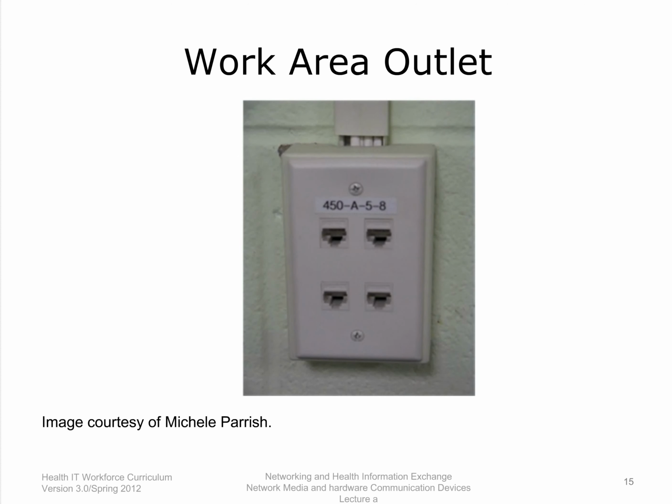Slide 15. Each work area must have a minimum of 2 information outlet ports, one for voice and one for data. A patch cable is used to connect the outlet to the node.